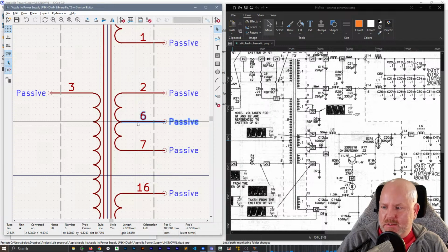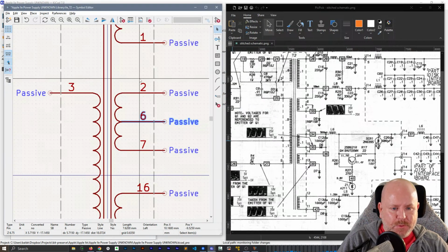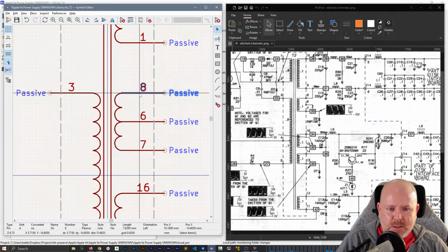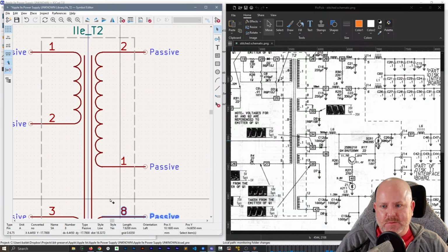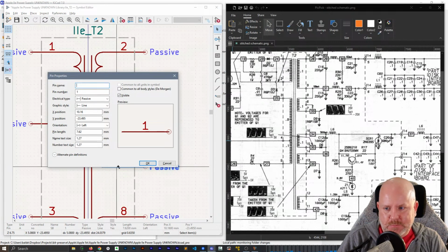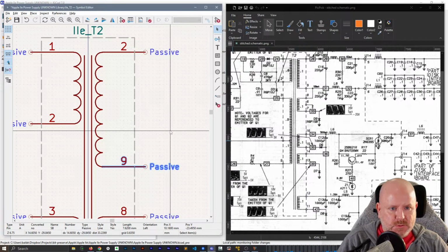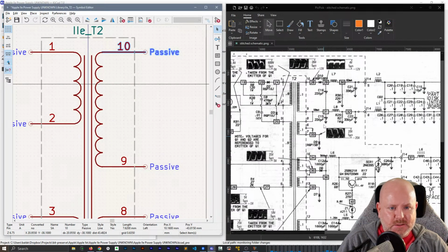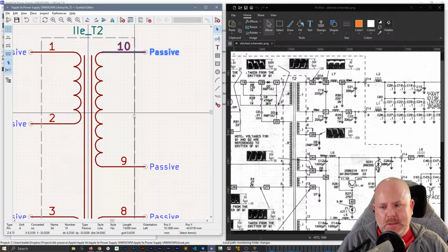I would recommend that you post pictures of either the datasheet and/or the connector to Ask Electronics on Reddit, and people will usually be able to help identify the connector. The other piece of information I would add is if they have a pitch, because somebody might be able to point you towards a series that has a compatible pitch.